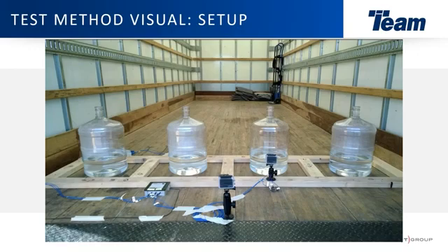So that's collecting field data, and there's another accelerometer to the right of that by about 24 inches or so. And then just to the north of there, on the other side of that second water jug, is a third tri-axis accelerometer. The reason we're doing that is we're defining a plane and helping capture better data on what's happening across that entire surface, as opposed to a single point of contact by one tri-axis accelerometer, or even various single axis accelerometers.